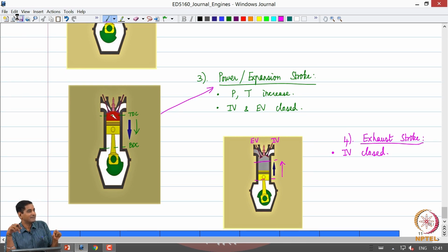Ultimately, if you do not have any of those, you just have a pipe, obviously you are dumping to the atmosphere, and there is going to be a significant delta P which will enable that flow. But once you start adding all these elements, you are going to have what is called a significant back pressure. Then we need to start worrying about what will happen. That we will figure out as we go.